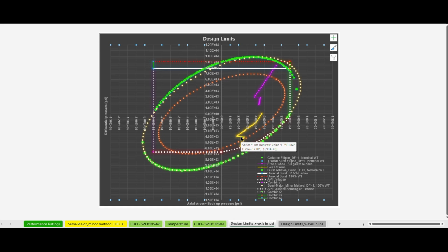Because you know that the strain is zero in the cemented interval, we have an exact solution with the Poisson ratio. However, above the cemented interval, the solution is not that certain. That's why we basically took a midpoint approach both on the thermal stresses and the ballooning related stresses. So that's why you have this spike over here.